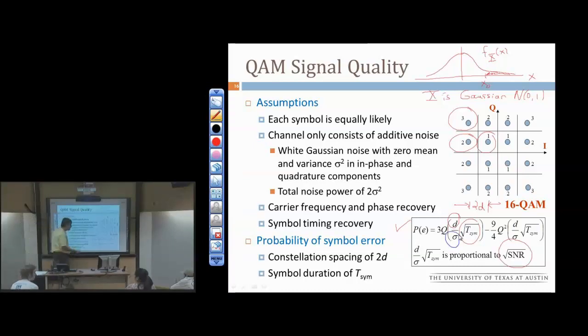All right. So if you increase D, it means what? You increase the average power and the peak power in the transmitter. So you crank up the power in the transmitter, and that's going to give you better SNR by the time you go through the receiver. Go through the matched filter and the downsampling. And so by the time you hit the decision device, you have increased SNR because you've increased the signal power at the transmitter. You cranked up the volume, whatever. So you've got more signal power. That's just going to be more power at the transmitter side.